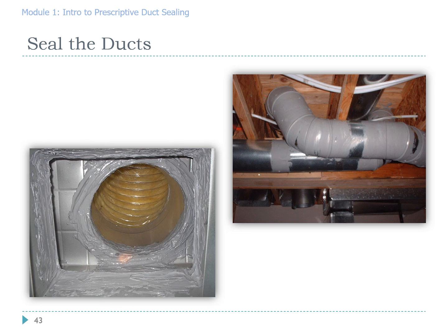If you apply it too thin, it's artwork. It's not actually energy saving work at all. As you can see here, there's a lot of mastic on everything that might leak. We've got all the gores covered over here. We've got the slip joints covered. This is a takeoff from a manufactured home. And as you can see, there's lots of mastic. That's not going to leak.